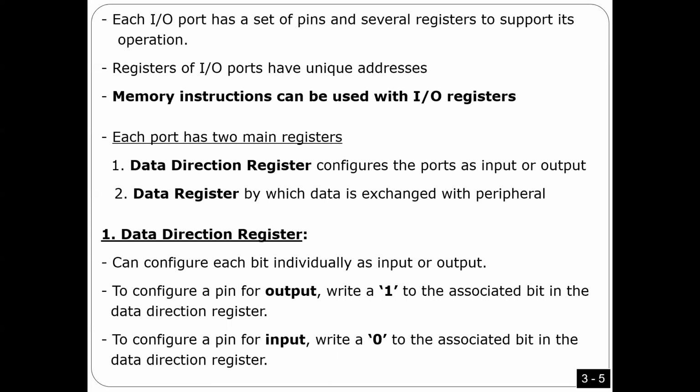I explained something like that in the lecture, guys. If you have a pin here, this pin is connected somehow to a byte here, right? If this pin is output and in this byte I put logic 0, you are going to put 0 volt here.